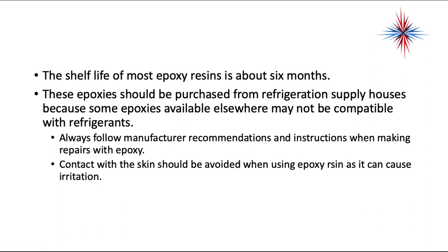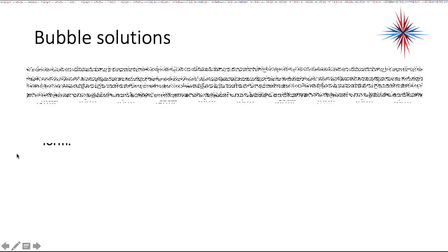Now, just as a hint, when you're sealing an evaporator with an epoxy resin, it doesn't hurt to put the system into a slight vacuum, not a deep vacuum, a slight vacuum. That will pull the epoxy resin into the leak. Okay?